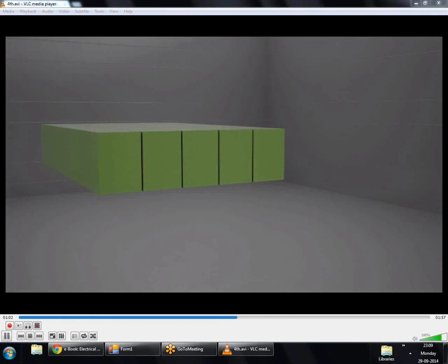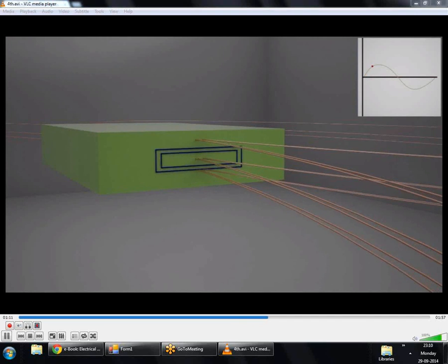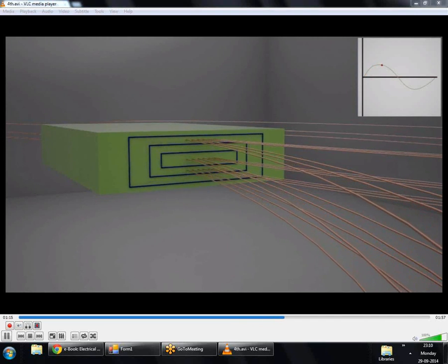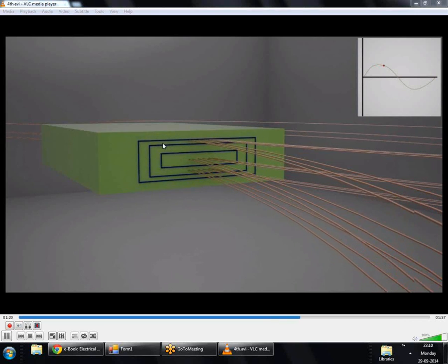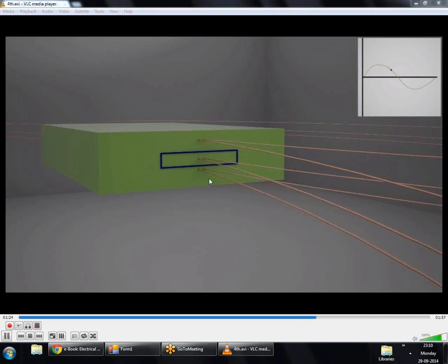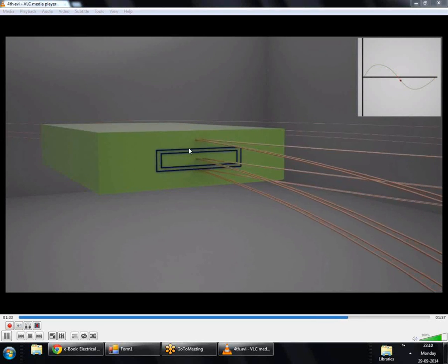Now, due to this alternating magnetic field, a current starts to develop inside the ferromagnetic core. The ferromagnetic core has certain resistivity, and due to that resistivity we start to experience ohmic losses. You see in this animation that as the flux lines increase, the magnitude of the current flowing through the ferromagnetic core, shown here in the black loops, starts to increase.